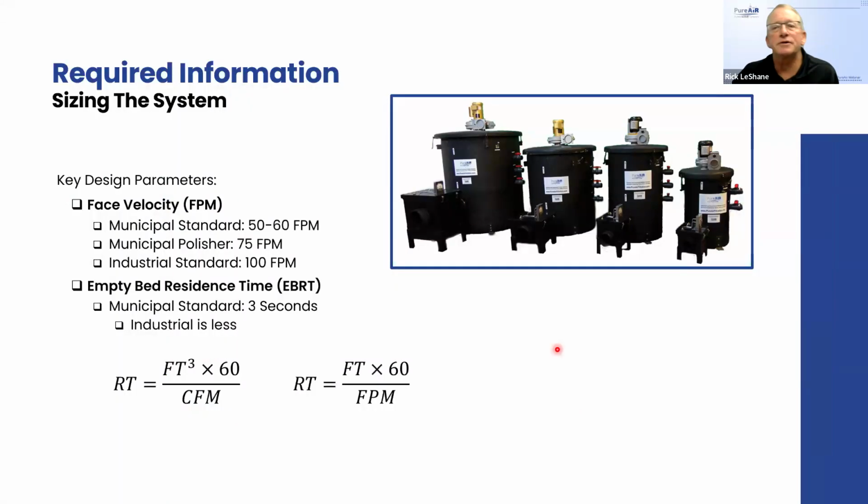All right, here's another key in sizing a system, and it's your velocities. Again, your face velocity, feet per minute. The municipal standard is 50 to 60 feet per minute. You probably see 60 more than anything; it's probably the more common.